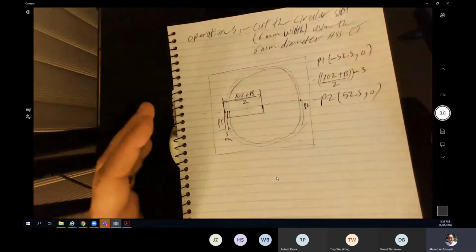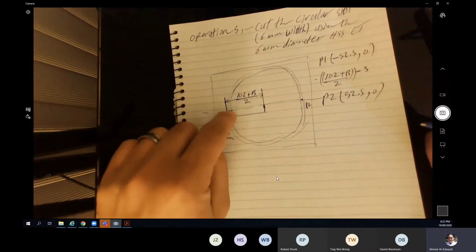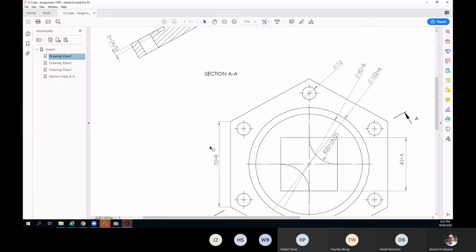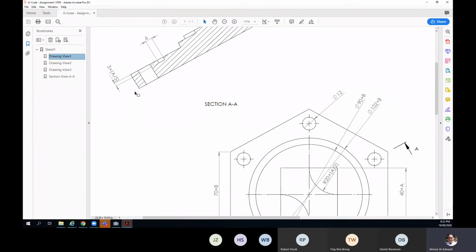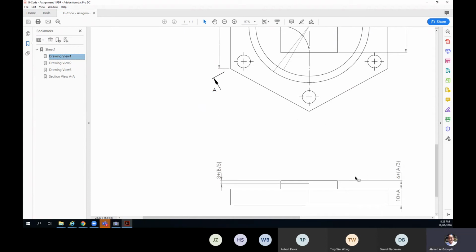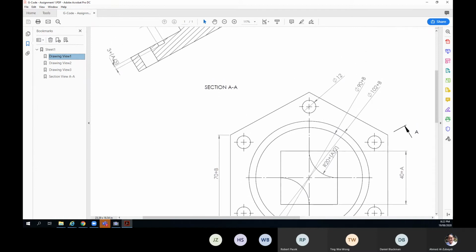Now, the only thing we have to do is write down a code, bring in the cutting tool at the top of point number 1, and take it down to the depth of 3 plus A divided by 5 plus this depth. Because we are referencing from this height to the lower level, everything is referenced from this height. So 6 plus A divided by 3 plus 3 plus A divided by 5, and all going to be in negative. That will be the depth of the slot from the top level.